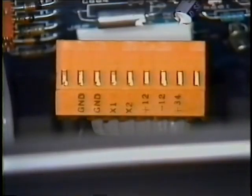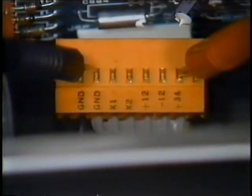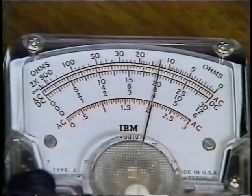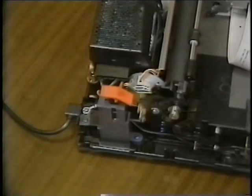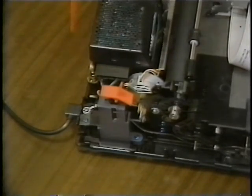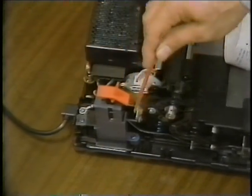To measure the voltage on the 34-volt pin on the power supply connector, reverse the leads again to read positive voltage. This pin should read from 20 to 47 volts DC. Caution: turn the machine off and wait 2 minutes before plugging the power supply connector into the printer board. This is to prevent damage to the printer board. When taking voltage readings on this machine, when the power supply connector is plugged in, you can connect the common meter lead to the machine frame or any of the ground wire connecting points shown here.